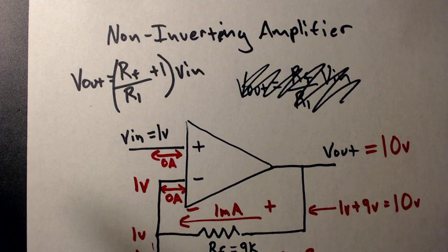And I'll go ahead and leave this lecture as this. Okay? So we really covered three very useful and crucial circuits when beginning with op-amps. We covered the comparator, we covered the voltage follower, and we covered a non-inverting amplifier. Those are the fundamental tools that we need when we're starting to interface analog circuitry to digital circuitry. Okay? So I'll go ahead and leave this off there.